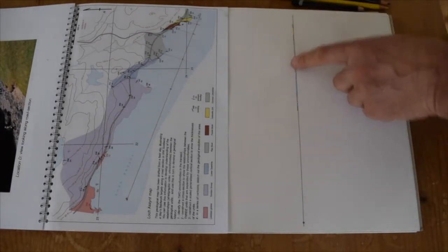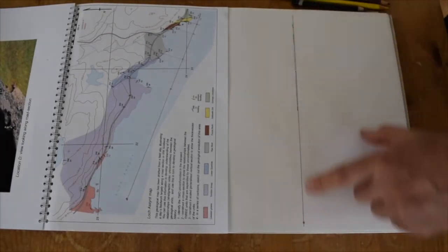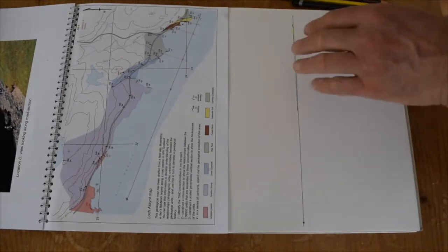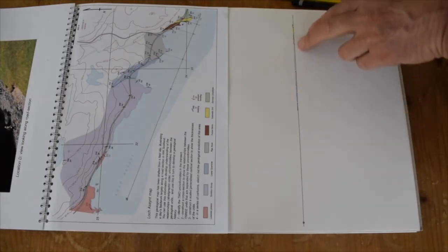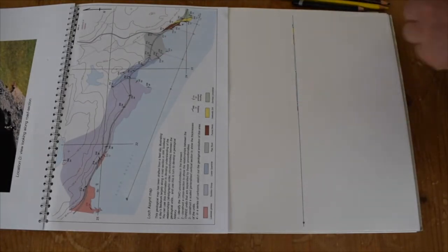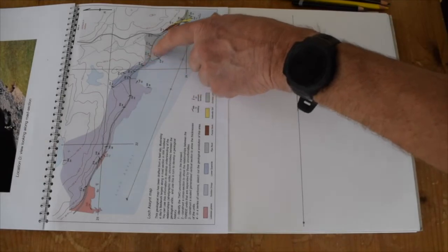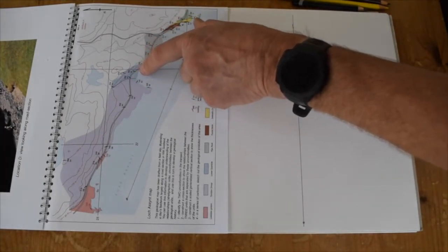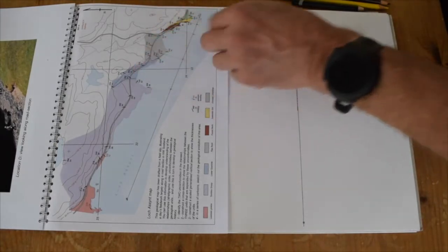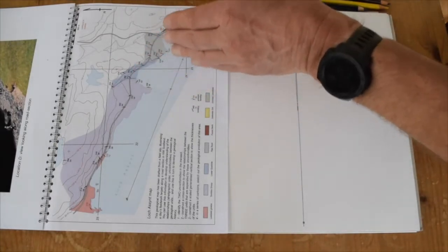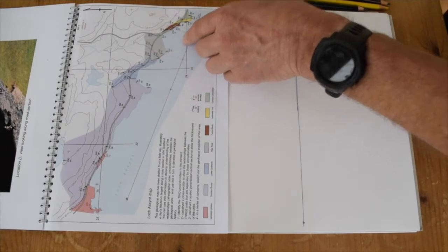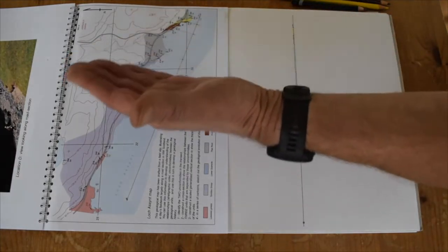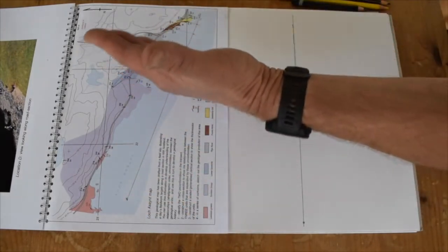So that's collected the geology along the level of the profile. Now we need to extrapolate above and below ground. For that we need to have some information about the orientation of these materials in here, these rocks, and we can use the dips that we've got in the stratigraphy through here, because we've established that all these units are conformable. I'm going to make this simple by just picking one single value for the dip, and let's just pick 12 degrees, dipping this way, so the cross section is drawn in the dip direction.